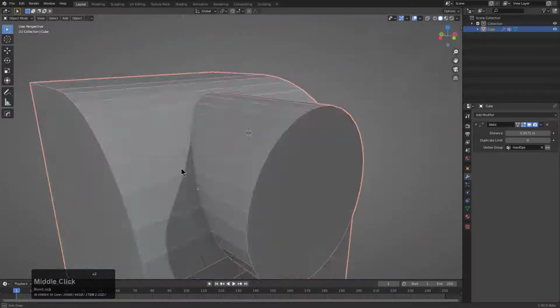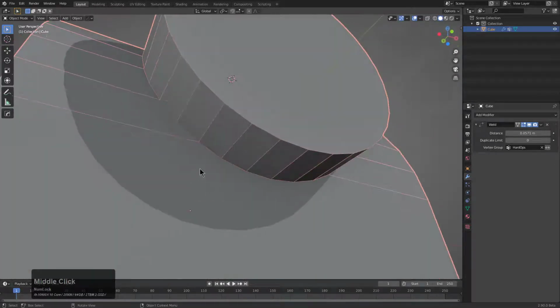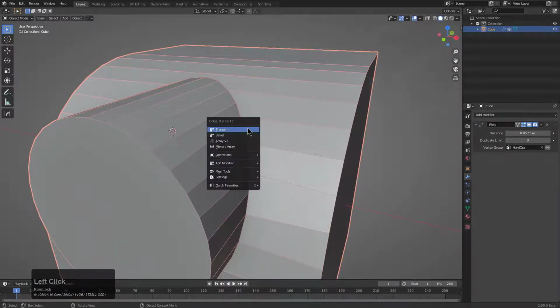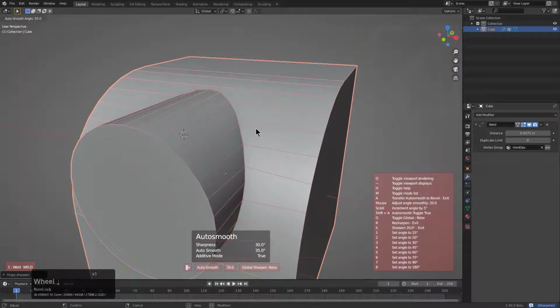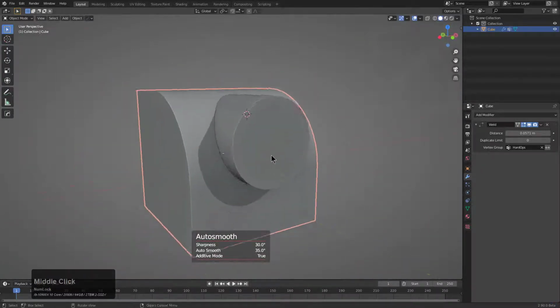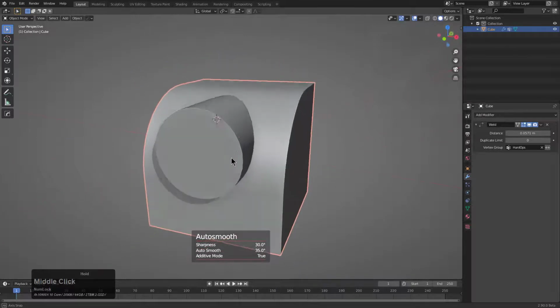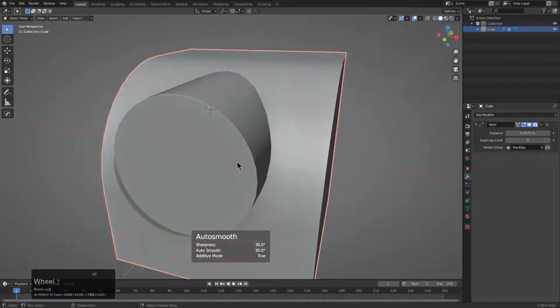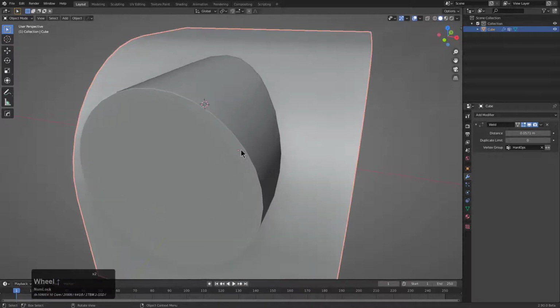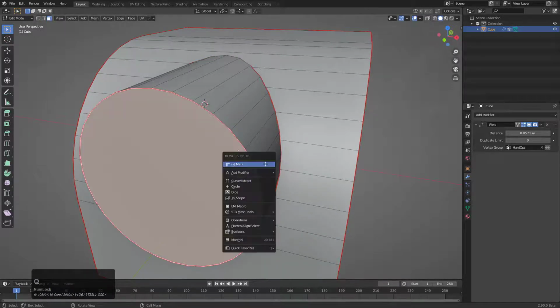However, it's important to be able to set up vertex groups with weld in edit mode in order to get kind of a controlled weld happening, because it can be the difference between getting a nice surface going and having something that's a bit of a shading disaster. But something like that can come in very handy for just bullying a curvature into another curvature area, and then just using weld to just kind of mitigate it in the meantime until you go in and give it a finer fix. So tabbing back in, that covers basically all of mark in edit mode.